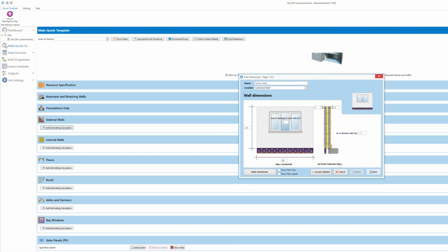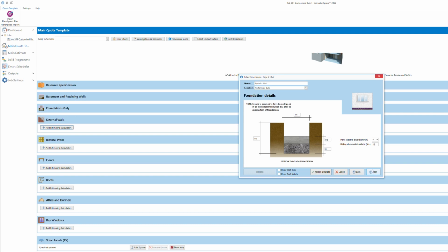They're all identical, and all you do is go through each section here. On the footings, obviously it's going to be a 0.6 with 600 millimeter. I always go 0.7 to allow. Sometimes the dig's a pain in the arse. Sometimes you're digging up other things with it. Always allow a bit extra, okay? So 900 down, which is all we need. That's all good.